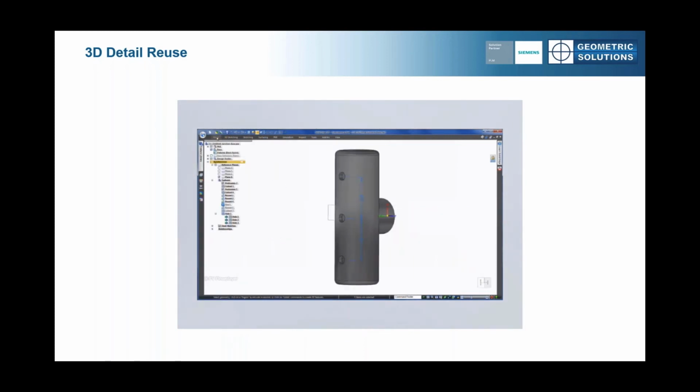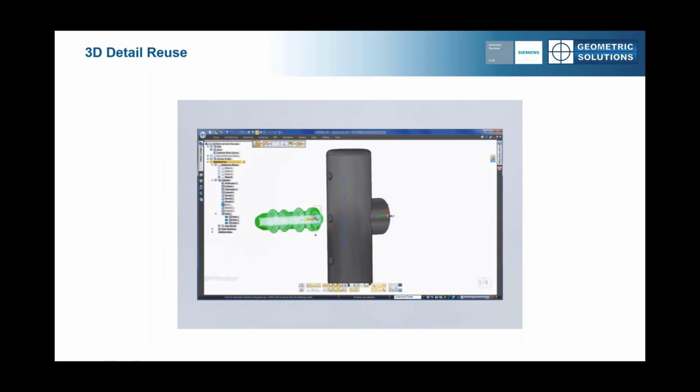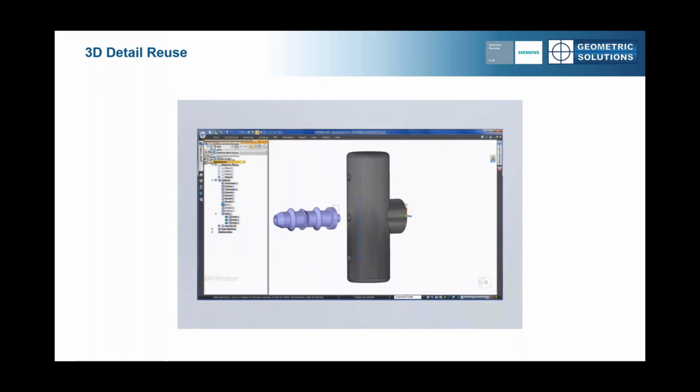Back in our custom fuel adapter, we just paste it in, again using the Windows shortcut Control-V if you like, and you can see our steering wheel is just where we left it, so placement becomes a simple task of snapping into place. And if you think you'll be using this detail again in the future, you can just store it away in the library. All you have to do is open your library pane and paste it into here instead. To reuse it, just drag and drop.